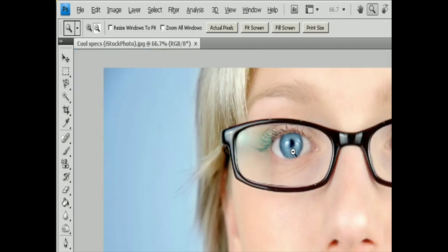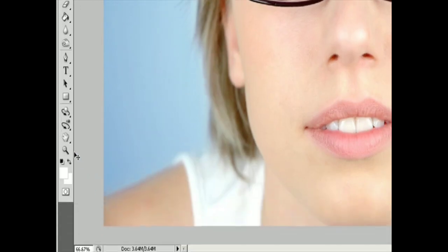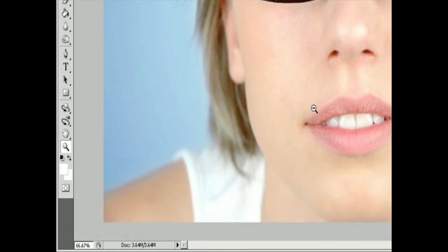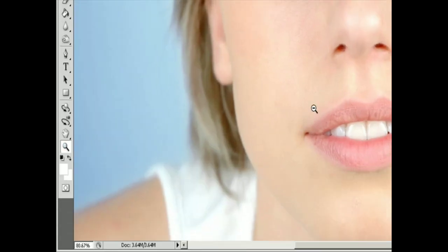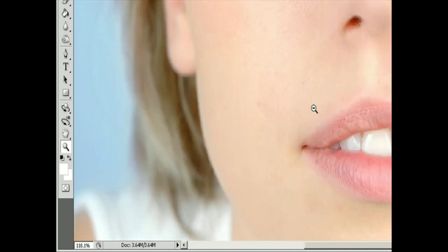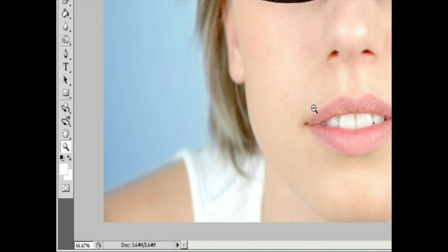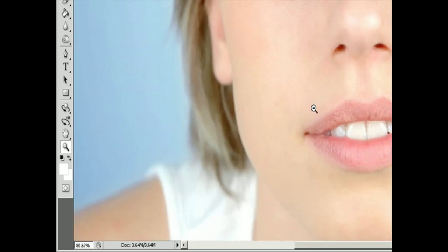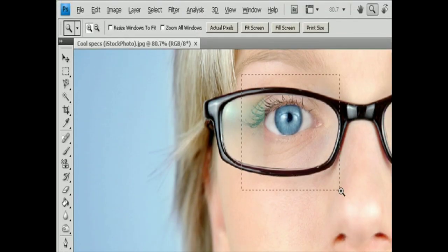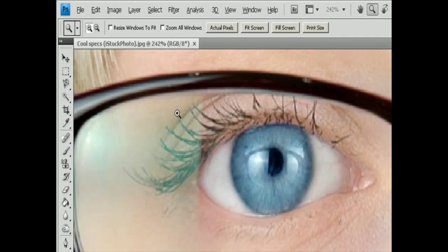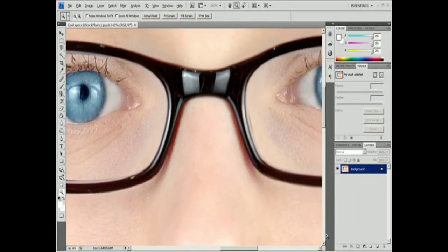Select the Zoom tool and then click-hold in the image for a continuous motion smooth zoom in. Alt-click-hold in Windows or Option-click-hold in macOS to continuously zoom out. Select the Zoom tool and drag a dotted rectangle marquee around the area you want to magnify. To move the marquee around the artwork, hold down the spacebar and continue dragging until the marquee is in the desired location.